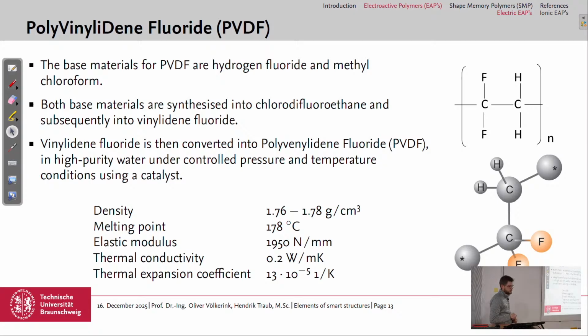So why would you say it's a multifunctional or more functional material? Do you have an idea? And why could it be not a multifunctional but only a functional material, if we think about the definition of a multifunctional material? So if we have the piezoelectric properties, we can use it as a functional material, we can activate it through an electric field, but to be a multifunctional material, it should also have load-bearing capabilities. And compared to other structural materials we use, like GFRP, CFRP, aluminum, the elastic modulus is really low, about 2 gigapascals. So here is a square missing, I've seen, so it's Newton per square millimeter. And therefore, I would say PVDF is more functional than a multifunctional material.